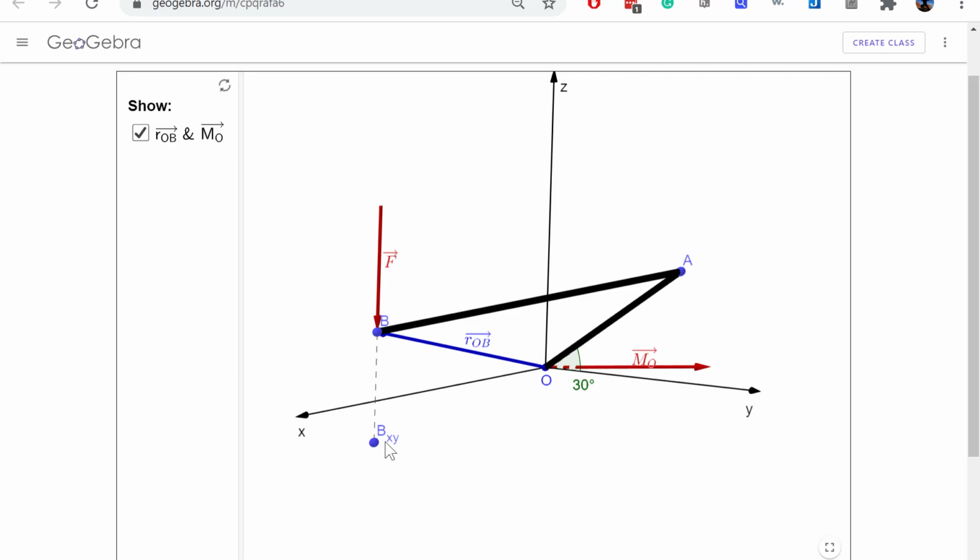So essentially it says that this force is causing rotation around this axis, MO, with a magnitude equal to the 537.6 inch pounds. Okay, so that's spatially what this is saying. So moments are vectors, they're just a vector of rotation.